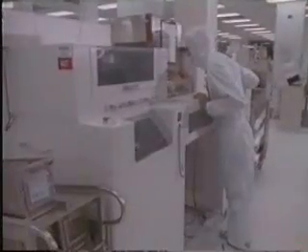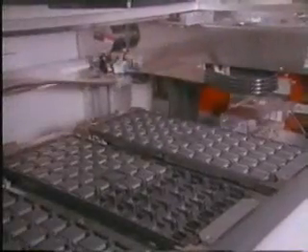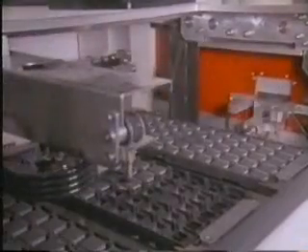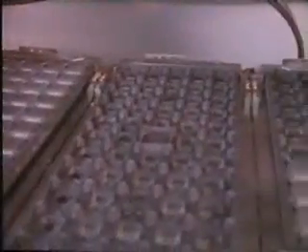This large computer controls 2 testing handlers. Inside the handler, we see the chips move to the testing region. An electrical socket tests each lead to determine performance characteristics. Depending on the test results, the chips are sorted as those that meet specified requirements, those that meet lower requirements, and those that have failed.